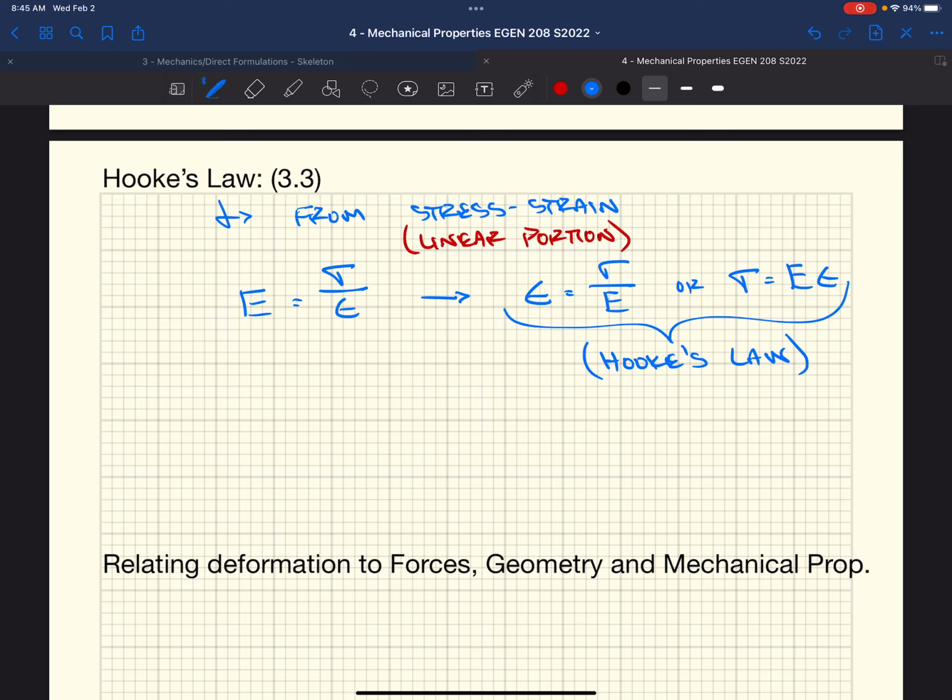Ceramics are very brittle materials. They don't get any permanent deformation. And so they really follow Hooke's law, the stress-strain response. But like steel or plastic, some of those things that get permanent deformation, they follow Hooke's law on that linear elastic portion. The second you get out there, this behavior doesn't match. You have to come up with a new, what we would call constitutive relationship, which relates strain to stress. But for a lot of materials, this is what we deal with.